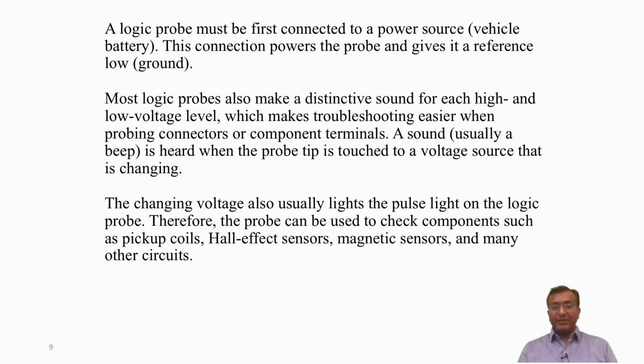Take another example. If we are testing a modern car's ABS or airbag with a continuity tester that has its own battery, it could apply too much voltage and cause damage. In these cases, an LED test light or a high impedance multimeter is safer and won't harm the sensitive electronic components.